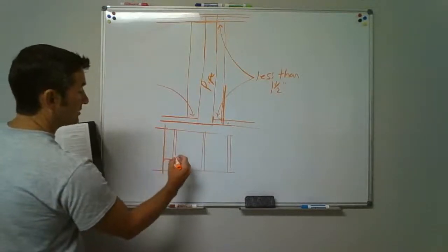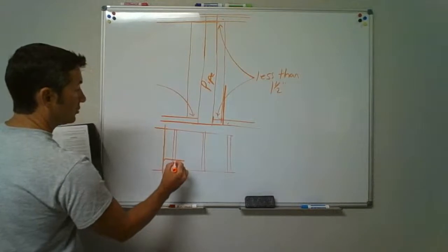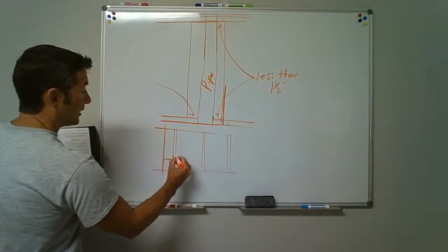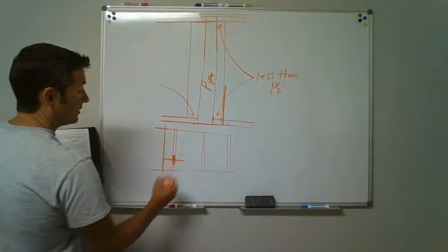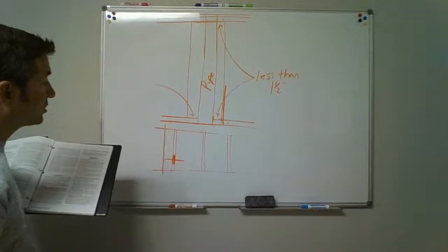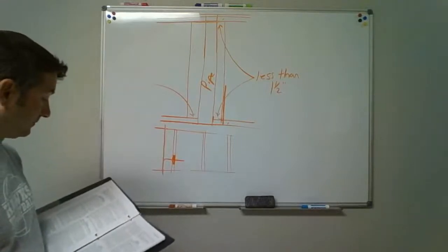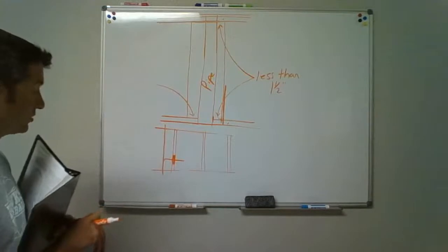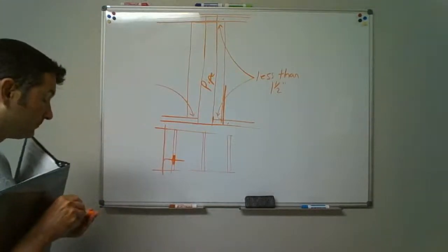We've got a protective shield plate if it's closer than 1.5 inches to the edge of the framing member. And this shield plate only has to cover that 1.5 inches, just the amount where the pipe is going through would be fine. It gives you the plate thickness as well that's required on those.